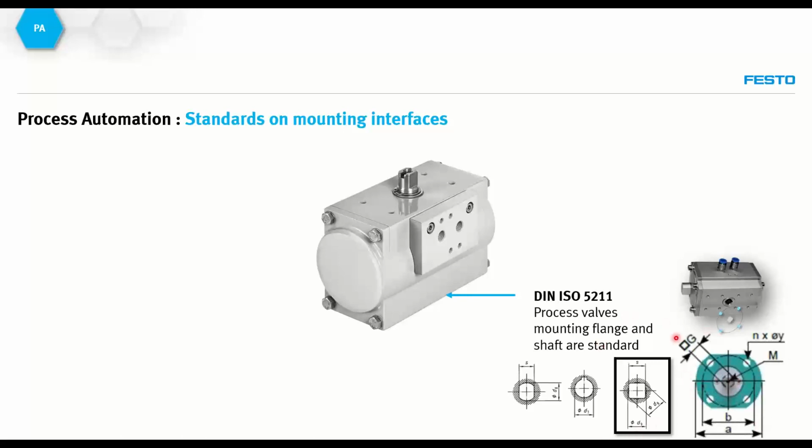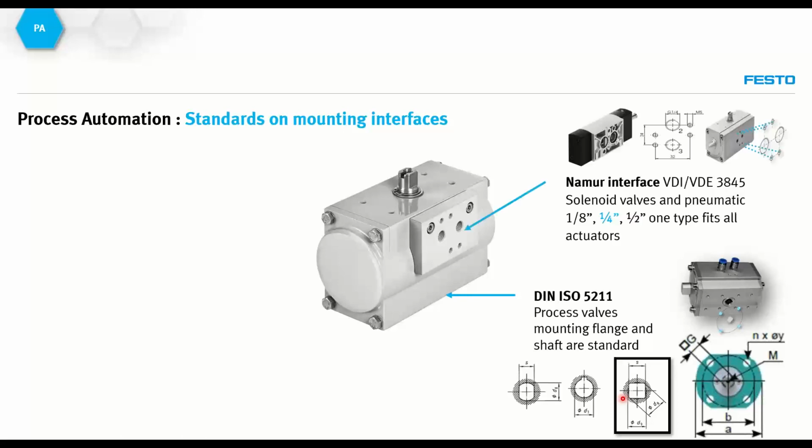Talking about the shaft dimensions, as we can see in this ISO, we have three types or shapes of shafts. We have the double D, we have the round shape, and we have the square shape. Here to highlight also that the square shaft is the most common shaft used for these process valves. Moving on to the next interface, the Namur interface.